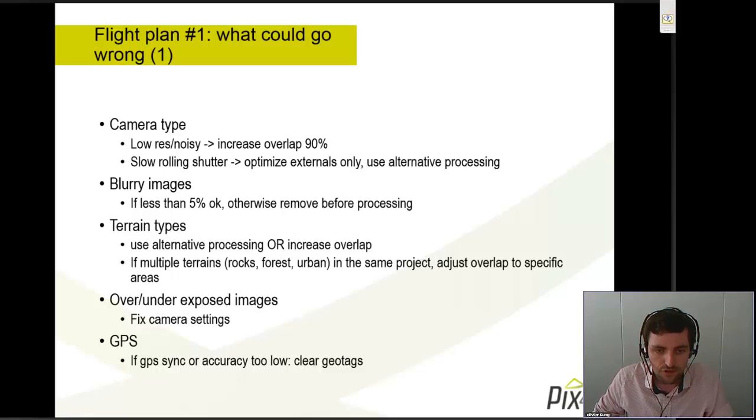If you cannot use this alternative pipeline because you don't have geotags which are good enough, what we recommend for this type of terrain is to increase the overlap.